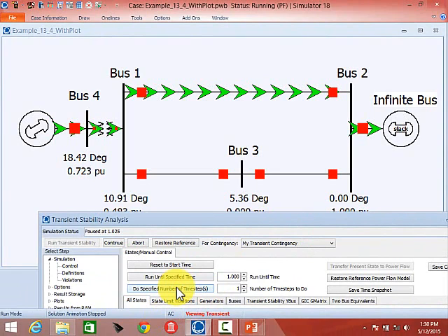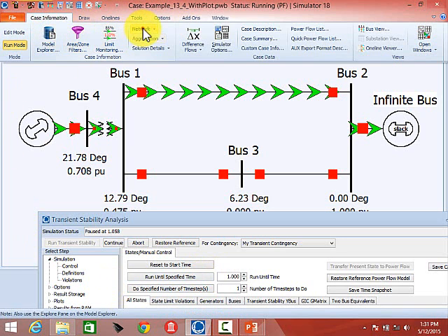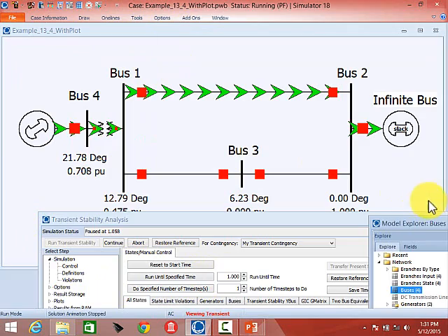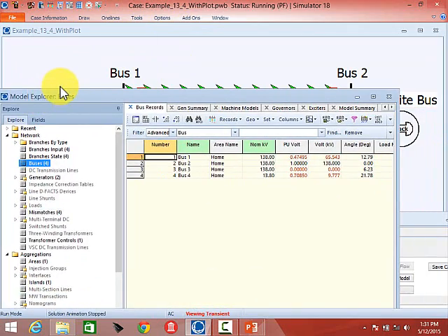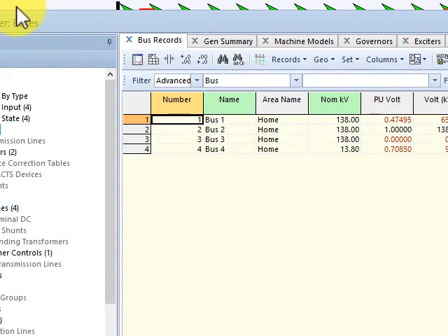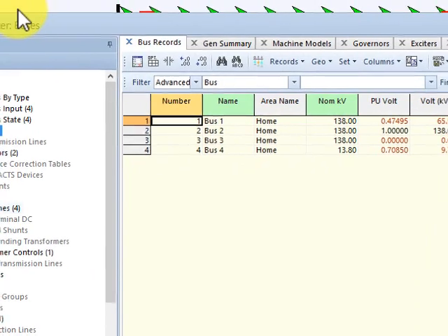We clear the fault, I think, at 0.11 seconds. So you can either run until 1.11 or manually time step to get to that. But this is showing you the details of what's going on. And you can look at this state with all the PowerWorld displays, like the case info, network, buses display. That gives you a lot of power when you're dealing with a detailed study. What's going on with this case? Very useful to get a lot of insight. And when we debug cases, we do this all the time.